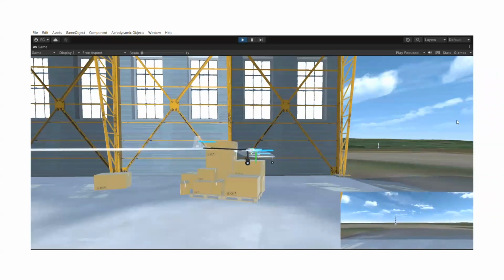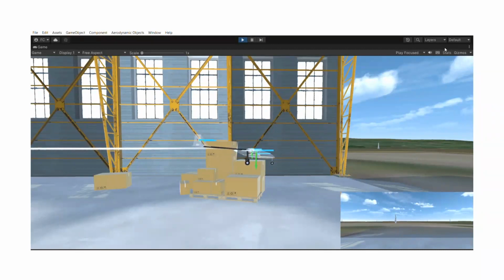As we can see, if we put the trim too far, the aircraft will pitch down or up. Also, as we could have seen with the CG, if we put the thrust too high, the aircraft will naturally pitch down as the engine is higher than the CG, so there will be more moment.